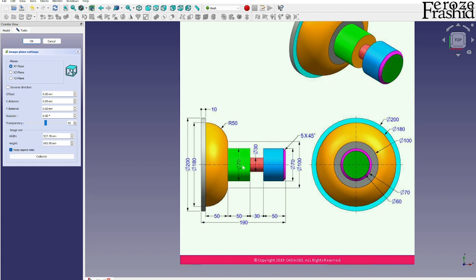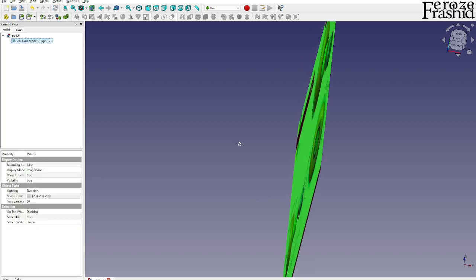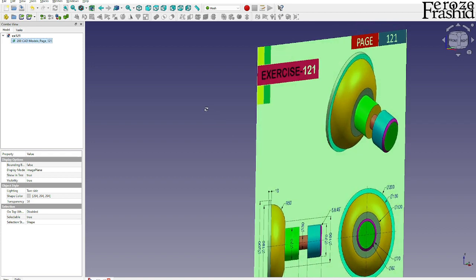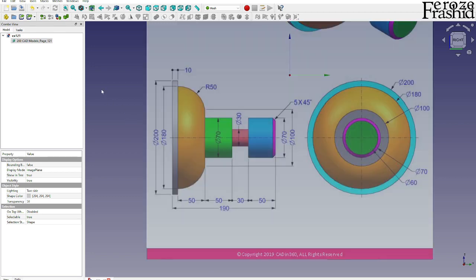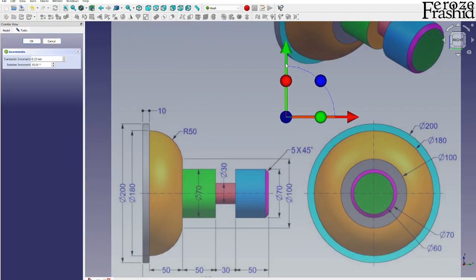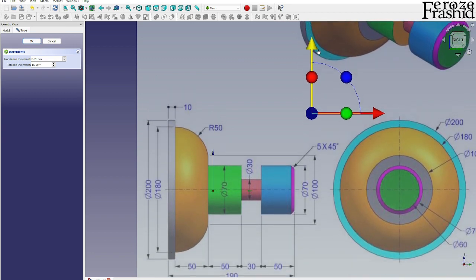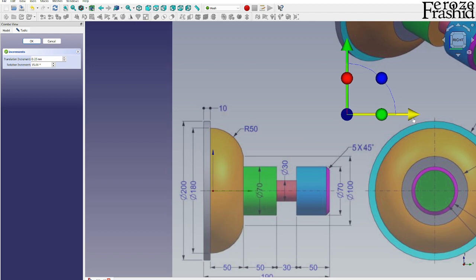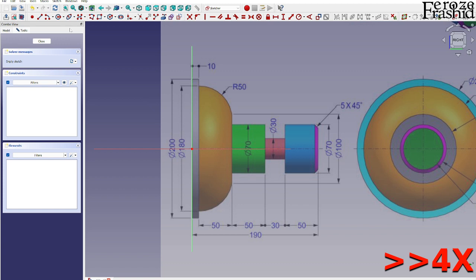This to me is the side view, say. So let's go ahead and place it on YZ plane, right? So that's on the side, and YZ is on the right. So I find that view on here, right view, and then bring axis cross to the view, AC on the keyboard, and then relocate the image where it suits best. So for this case, it will be on the axis and right there. And let's start sketching.